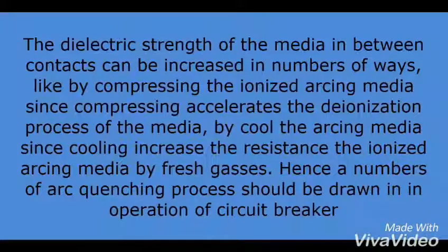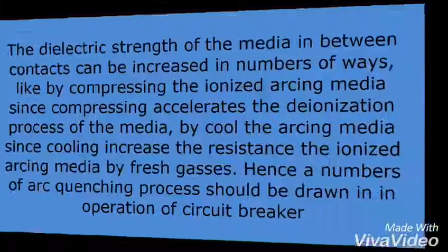The dielectric strength of the media between contacts can be increased in a number of ways, like by compressing the ionized arcing media, since compressing accelerates the deionization process of the media. Or by cooling the arcing media, since cooling increases the resistance of the ionized arcing media, or by fresh gases. Hence a number of arc quenching processes should be drawn in operation of circuit breaker.